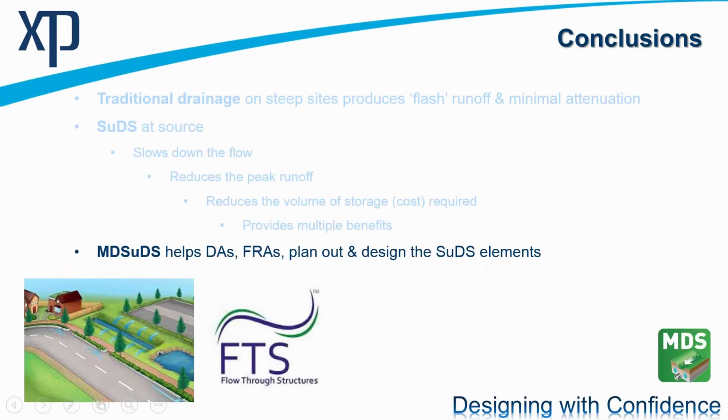So MicroDrainage SuDS can help us with this, not just for the initial drainage assessments and the flood risk assessments that Max was showing us earlier on, but also to design each of those SuDS elements and create a treatment train in itself. And as I mentioned, this is the software that will enable you to model the flow of the water through the structure itself.